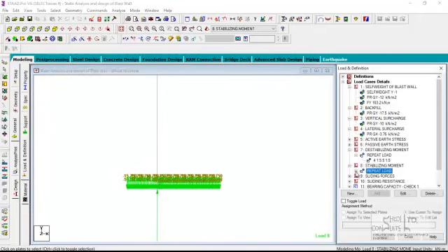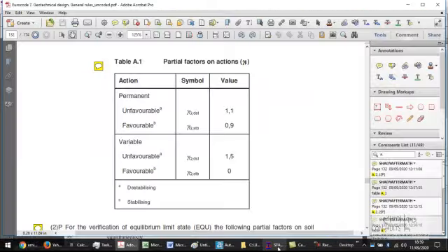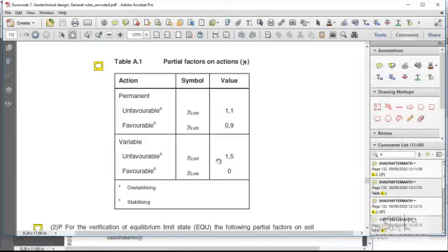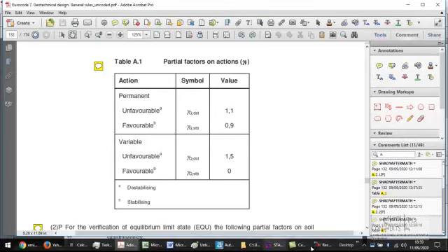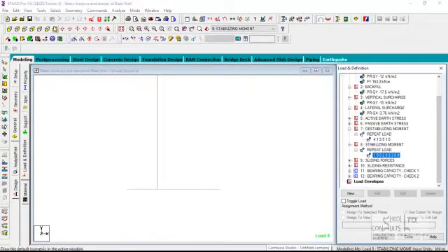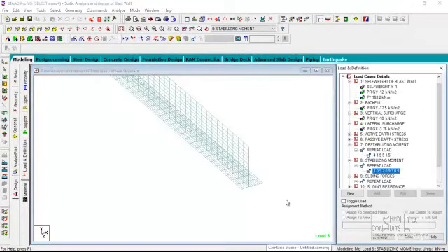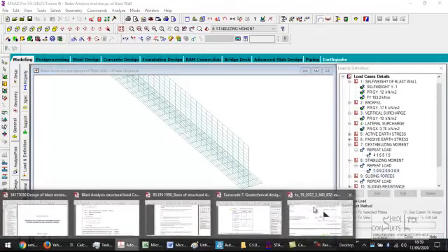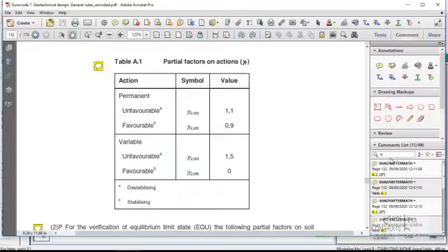So look at it, these are the stabilizing forces. If you watch very carefully, you see the partial factors of safety as provided for by the code. It says for live load you have 1.5, and then dead load you have 0.9. In the same vein, stability against sliding. Okay, let's look at what the code says about sliding stability.